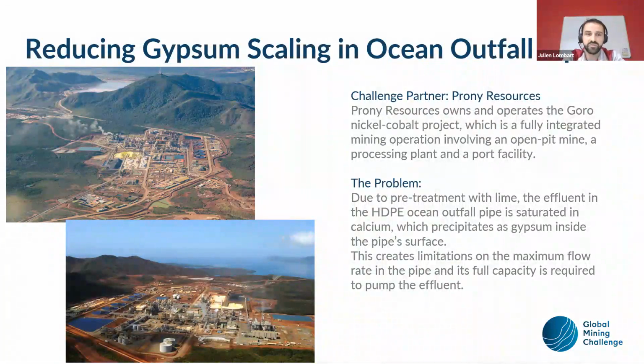After that, we have a lot of solid residue coming from this process, mainly residue from the leaching. So we have a residue of hematite and alunite, mixed with the gypsum created during the neutralization process. And all this solid is sent to a pond that you can see on the first picture. The solids settle in this big pond, and after that we pump the liquid back to the plant to treat it and to pump it to the ocean. It's our liquid effluent that we pump to the ocean after the treatment on the plant.